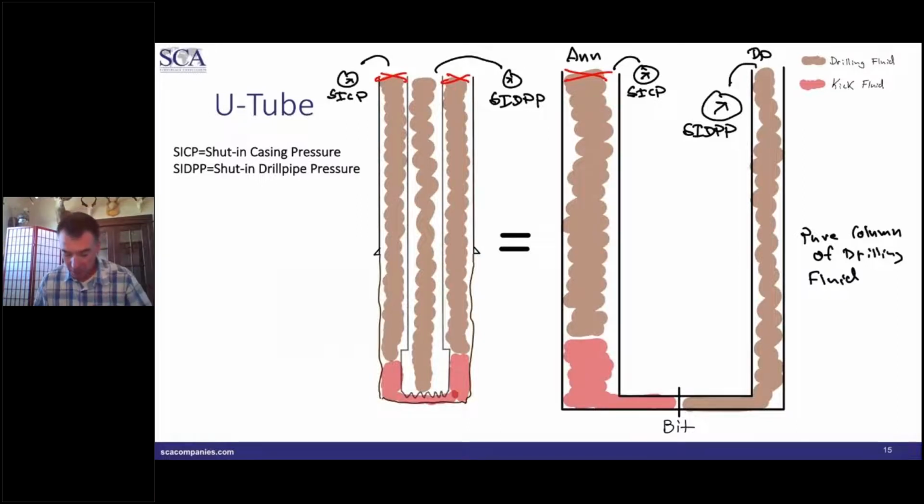Okay, the bottom hole pressure, BHP, of my annulus, if I'm shut in and it's come to equilibrium, equals P formation. And the bottom hole pressure on my drill pipe side also equals P formation, because they're equal. Both of these are equal here.